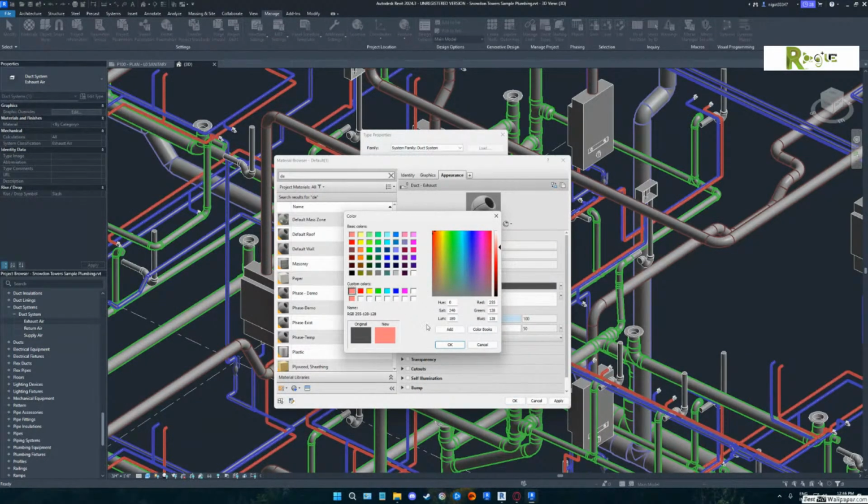Go to that one. Now listen, here's what I typically do. I created a crazy idea in my head, and that was if the material is lighter than the line, that means what's in the object is light. So if it's carrying a liquid, I make the fill pattern darker than the line. But in this case, it's carrying air.